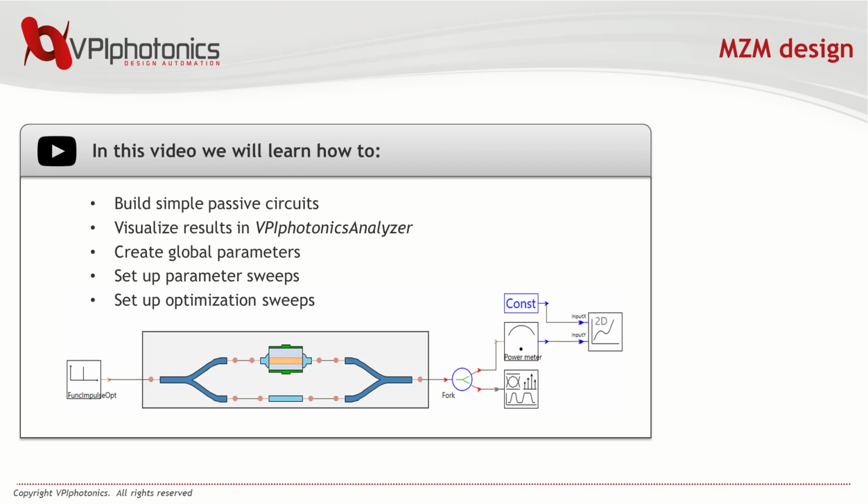Right now, let us speak about a simple Mach-Zehnder modulator. It is based on 2 Y-couplers, 1 straight waveguide and 1 tunable electro-optic modulator. All these elements are included in the DemoFab PDK, which is our toolkit for designing photonic integrated circuits, and their characteristics are represented by geometrical parameters.